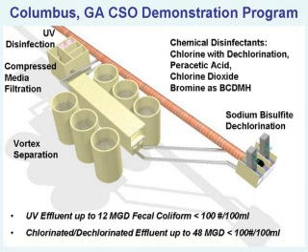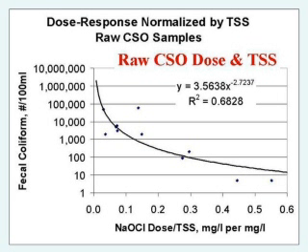But the peracetic acid, although it's pungent, there are other issues to deal with. It can leave a pretty much non-toxic effluent as long as you can get the peracetic acid in the effluent in the 1 milligram per liter, maybe up to even 5 milligram per liter range. Chlorine dioxide was tested in Columbus. It produces fewer disinfection byproducts than chlorine does.